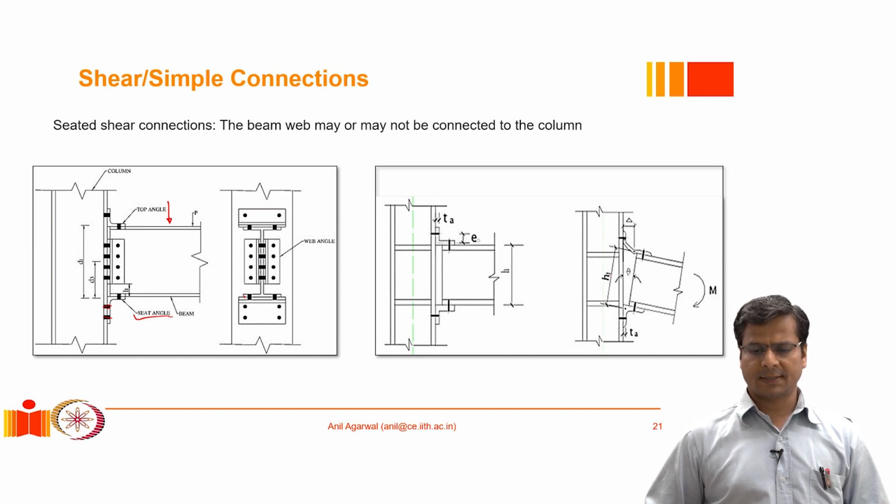In these cases, as I had discussed before, even though the connecting elements are sitting close to the beam flange, the connection does not behave like a rigid connection, because these angles themselves are very flexible when we pull them. If we push this angle in, it would offer a very high level of resistance.